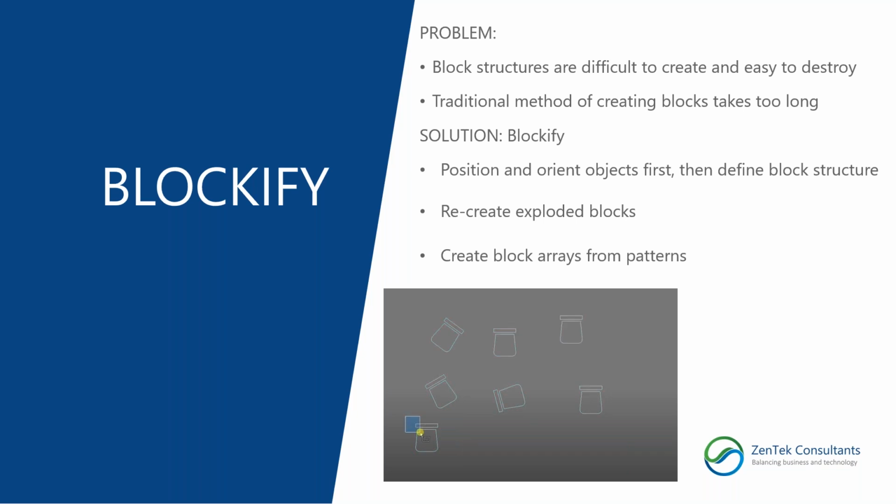The other issue that we're dealing with when working with blocks is it takes a lot of steps to create a block. For those of you that have worked with AutoCAD or with BricsCAD, the traditional method of creating blocks usually takes at least 3 steps. You have to draw the block, select the objects that are going to be part of your block, name it, and choose a base point or the insertion point of the block.